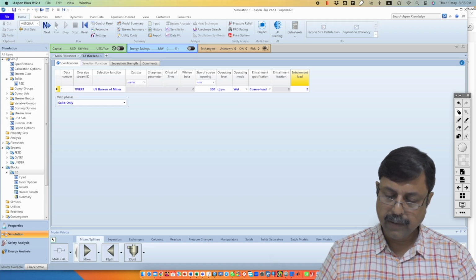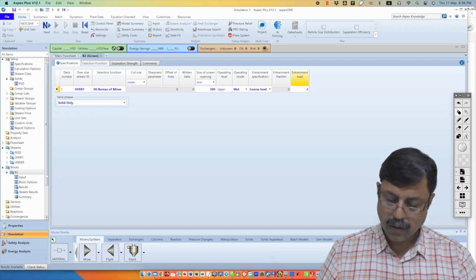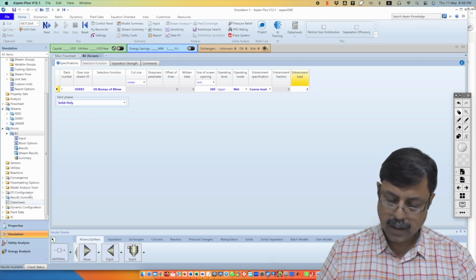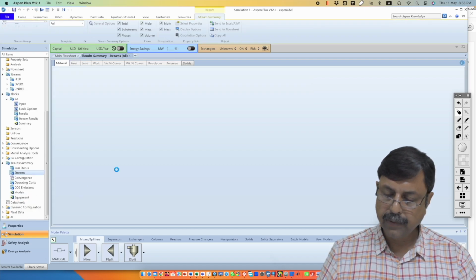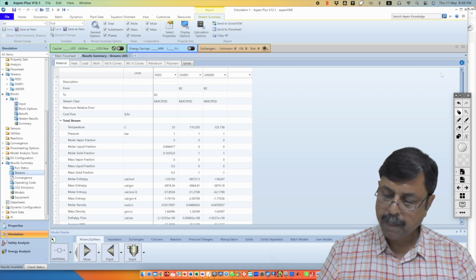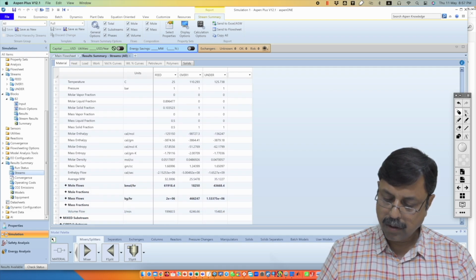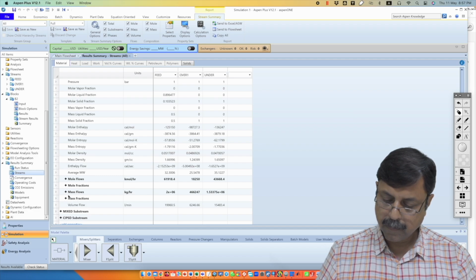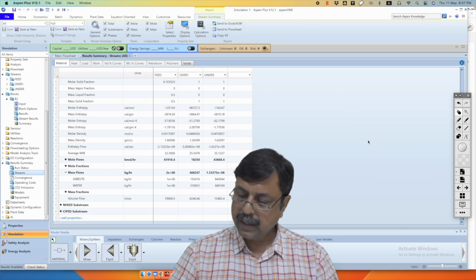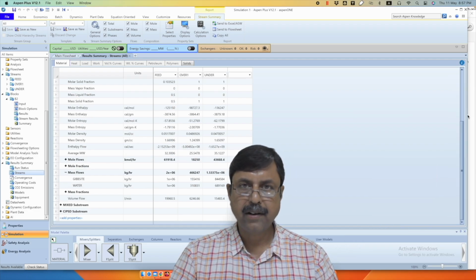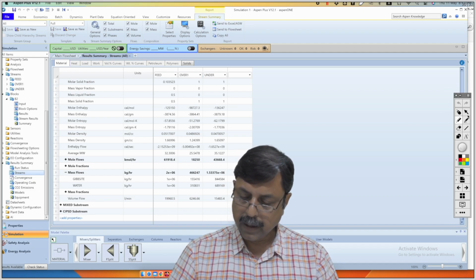Okay, now results available. You can go and find out the results in the result summary. So these are the streams. So you have, first check the mass flow rate whether the entrainment load has been calculated properly.